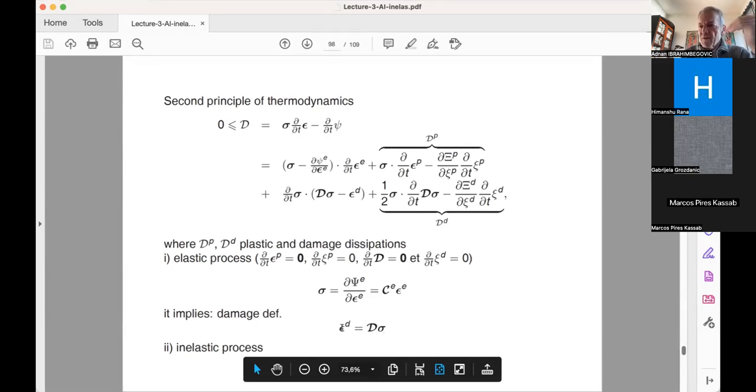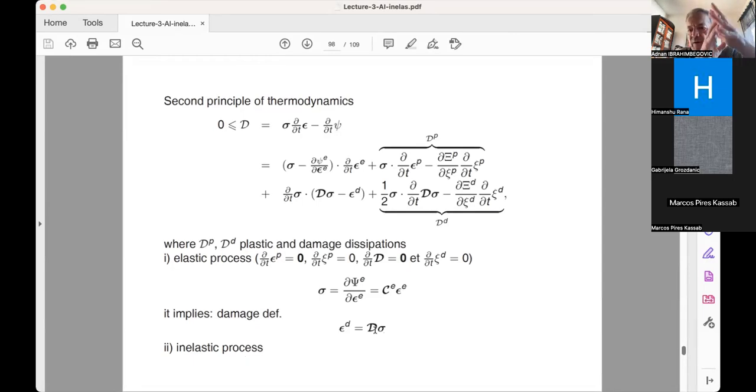So the damage variable, strictly speaking, once you know the stress and damage compliance, is not a new variable. It's just the way that you define this variable, knowing the internal variable called damage compliance and the stress that is just computed from the elastic strain. Please note that damage compliance, again, doesn't have to be one-dimensional. It could be in 3D, so we can do damages in shear, in tension, in compression, and so on and so forth.